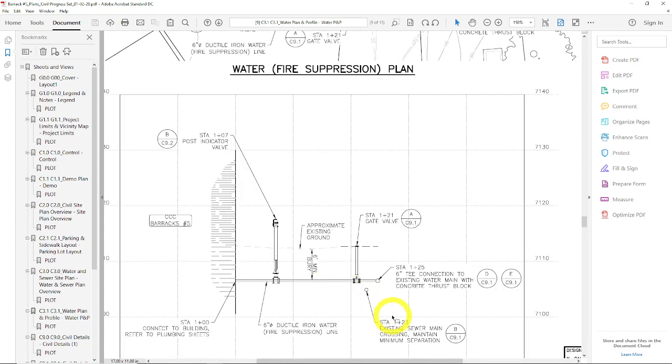This is a certain style of a pressure pipe network. There's probably some manual drafting on top of it to show these valves a very specific way. There's always a little mix of some manual drafting and using Civil 3D objects, depending on how advanced your styles are. This one probably has some blocks in it to make these gate valves look really ornate, but this will be more in Chapter 15, pressure pipe networks.